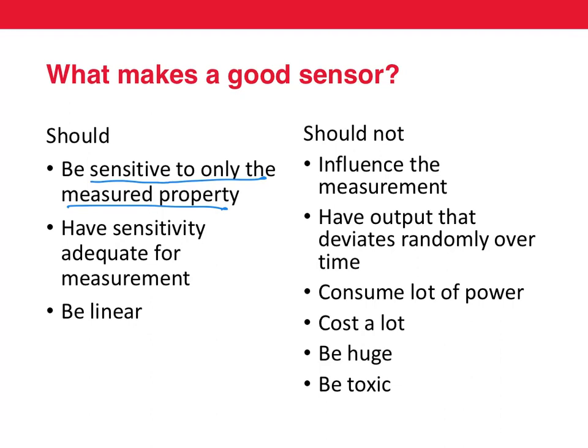Imagine trying to measure the weight of a person. Let's say we use a force sensor to do this. This sensor measures the force that the person exerts on the device as he or she stands on it. But the catch is that the sensor is also dependent on temperature. The larger the temperature, the larger the output of the sensor. So on a hot day, you measure your weight and you think you're overweight. It rains in the night and the temperature drops by around 5 degrees Celsius and your weight reduces by 1 kilogram. Now, that's not desirable, right? So we want our sensor to be sensitive only to force and not to temperature.